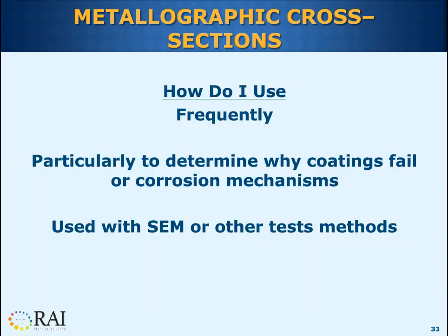So I use metallographic cross sections frequently. They're very helpful for me in determining why coatings fail or why plastics fail, and also corrosion mechanisms. And I use the metallographic cross sections with SEM or some of the other techniques that I will talk about today.